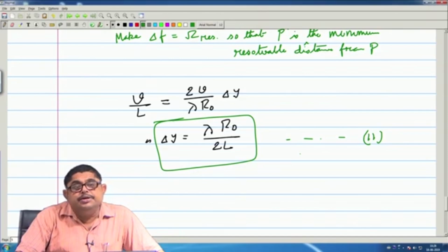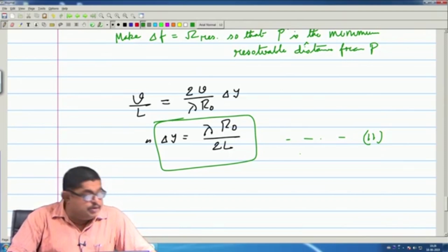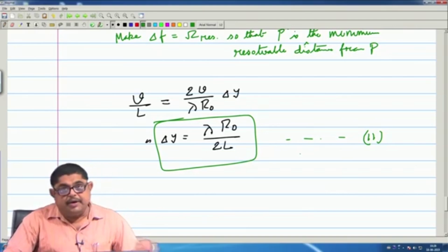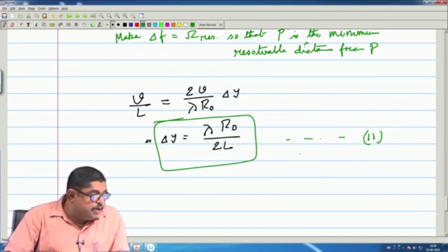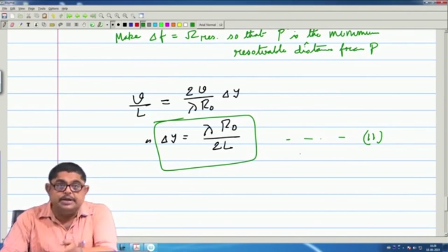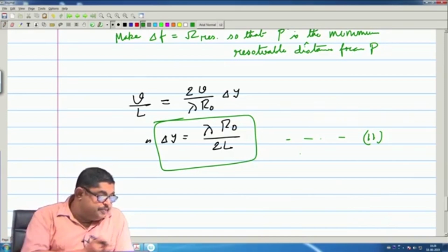In case of constant frequency signal, we will see that SAR's phase compensation is a linear function of time. In SAR filter, this phase compensation is a quadratic function, that we have already seen that phase is quadratic. Different Doppler filters are required for different ranges, and if R 0 is maximum, the slope of the f d versus t curve is less. Okay.